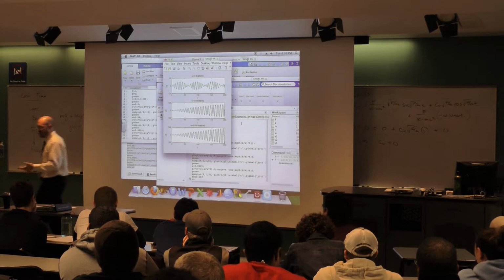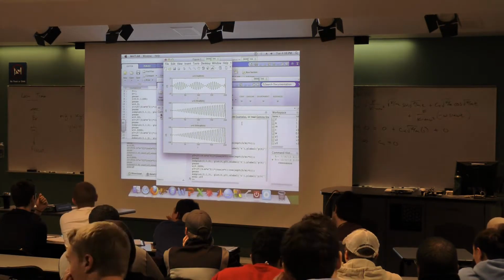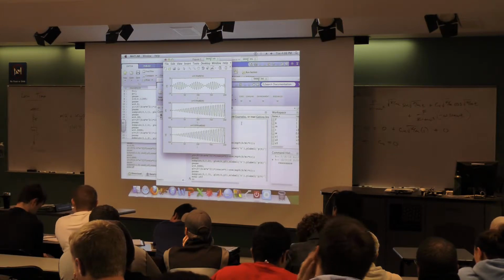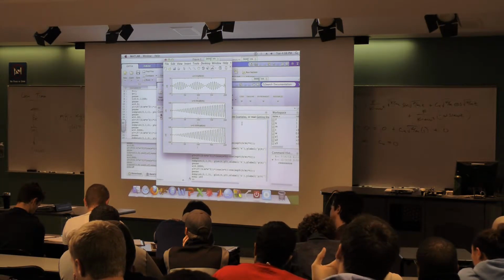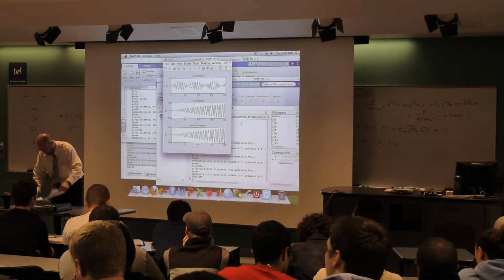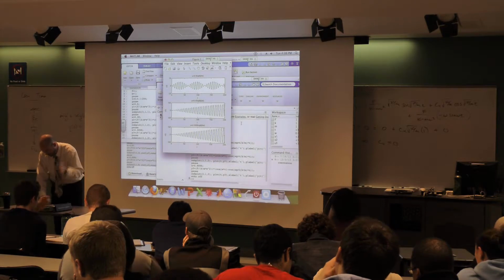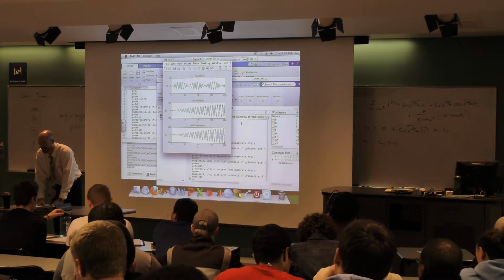So in design, what you basically say is, I've got to know what the frequencies are, and if I have to ramp up, I better get through the resonances in a hurry. I don't want to sit and operate something at its resonance. Okay, so that's the lesson on vibration design. You've got to worry about these things because otherwise you get this and stuff breaks. It's not good. Questions?